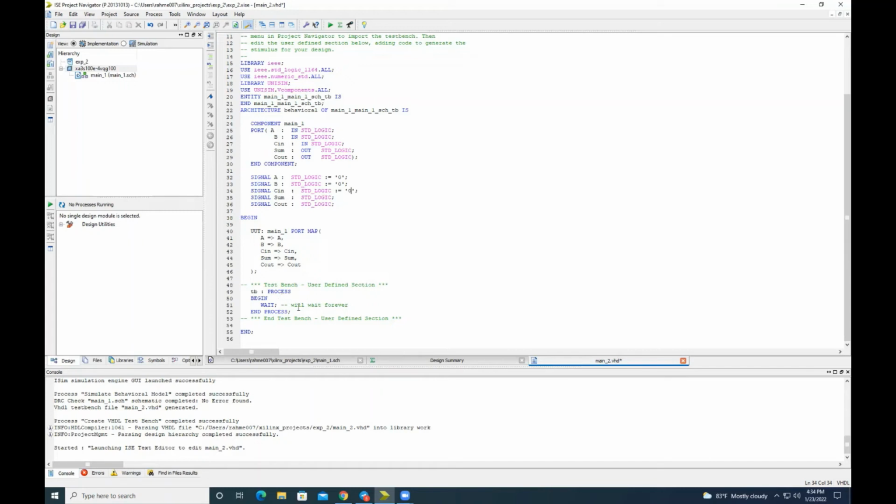The test bench you need to begin, right? How do you do that? You have 3 inputs, so you need to have 3 clock signal instantiations, right? So in that case, we can have the process. For instance, I can name it TBA, test bench for clock signal A, right? And begin the process, wait for 100 nanoseconds.